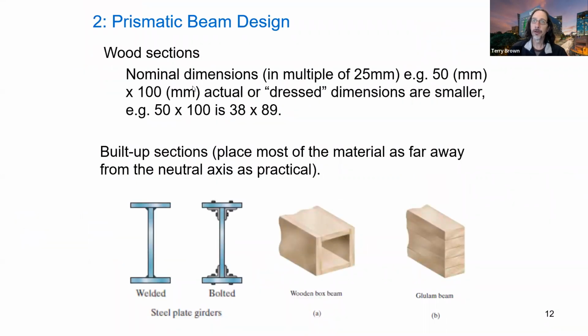Okay, the other thing to be aware of if you're building with wood, and there's standards for construction using wood and timber, you need to be aware of whether it's dressed or actual dimensions. Okay, so the dressed dimensions are actually smaller than the nominal dimensions. You just need to be aware of that.